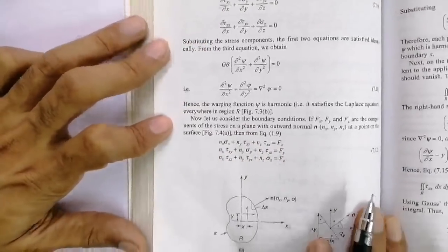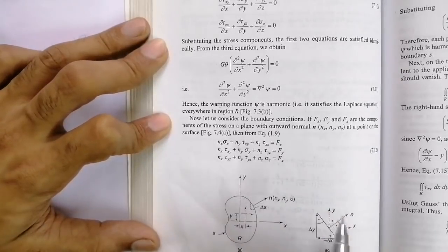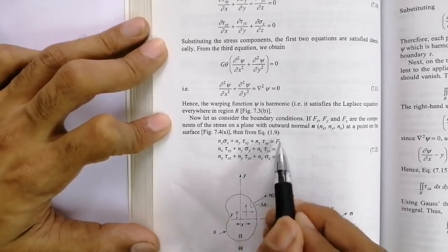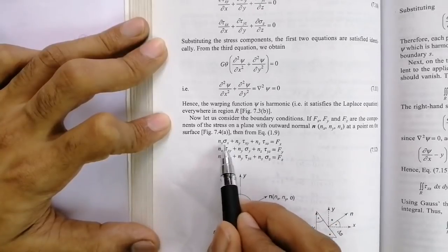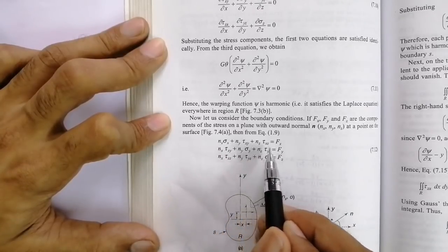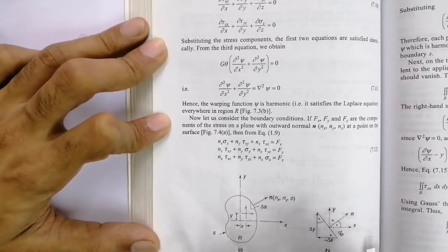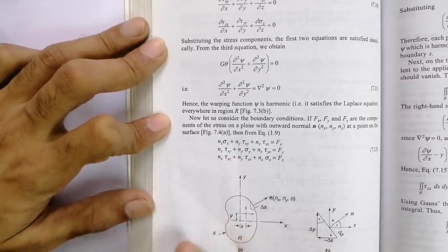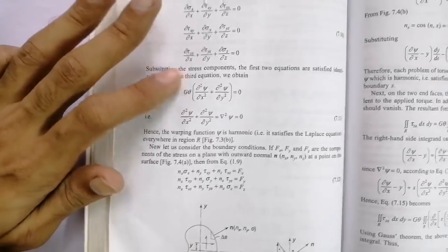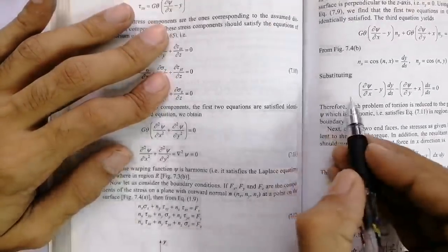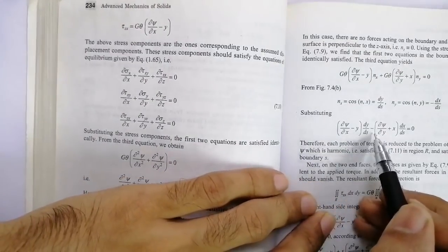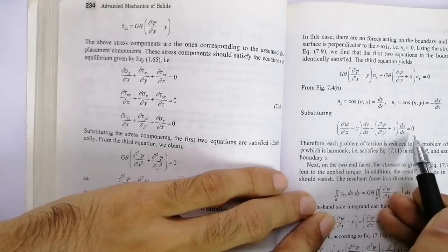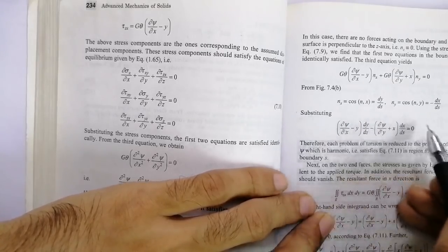Now let us move into the boundary conditions. For boundary conditions, you have to check the Cauchy's equation. Tx, here it is mentioned as fx. Why is it mentioned as fx here? Because in the boundary, force and stress are the same. So fx is equal to nx sigma xx plus ny tau xy plus nz tau xz. If you apply the boundary conditions, you don't go for these complicated figures. If somebody is feeling difficulty, by applying the boundary conditions you get the boundary condition as (dou psi by dou x minus y) into dy by ds minus (dou psi by dou y plus x) into dx by ds is equal to 0. So this equation you need to know.